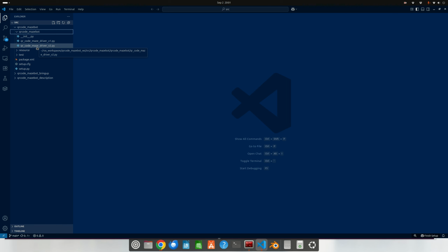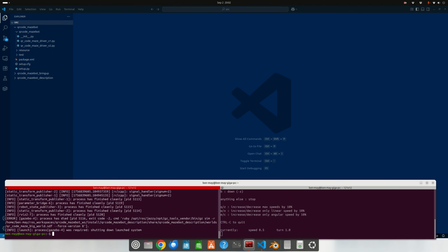V2 is a little bit more complex, a bit more robust, and it's leaning on the Lidar readings a lot more. An example being when it does its 90-degree left turns, when it wants to start off down another corridor, it's using the Lidar readings to effectively work out when the robot is pointing right down to the end of the corridor. It's not perfect, and there is a much better solution which I haven't done yet, which I'll talk through when we run the program. So let's get it running.